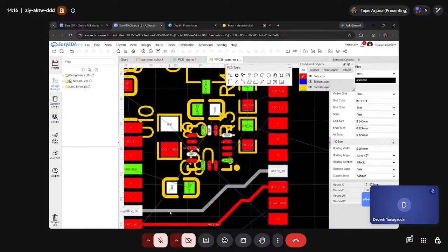So why does that happen? It happens for two reasons. If they are placed very closely, then when one signal has fast switching or high frequency, these two will have a capacitive coupling. Coupling means when current or energy goes from one circuit to another. So why is it called capacitive coupling? It is like a parallel plate of two capacitors, right?